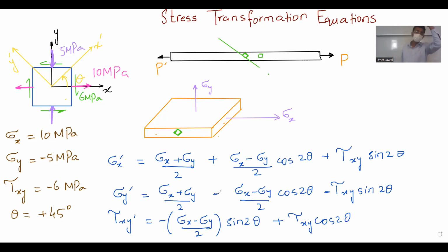Number one, somebody is applying the stresses in 2 dimensions. Either they are pulling it like this, or somebody is putting a torsion, whatever. As long as we are talking about a 2-dimensional stress scenario, I am allowed to use these expressions. What is the meaning? The meaning is that you see those yellow lines, one is x prime, and you cannot see that, that is y prime, the yellow line. So I have rotated my frame of reference.